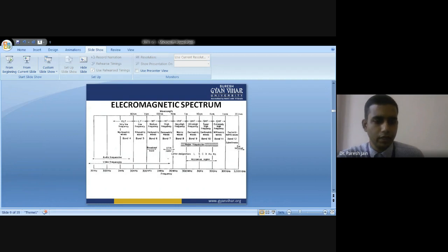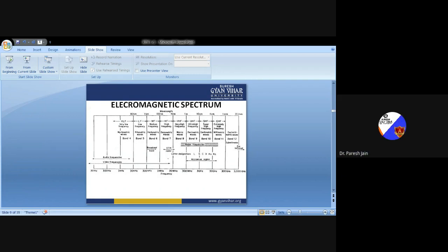So the answer is the ATR box, anti transmit receive box. Where is the RF attenuator used in a radar unit? Between the antenna and the receiver, between the magnetron and the receiver, between the magnetron and the AFC section of the receiver, between the AFC section and the klystron. Answer is C.